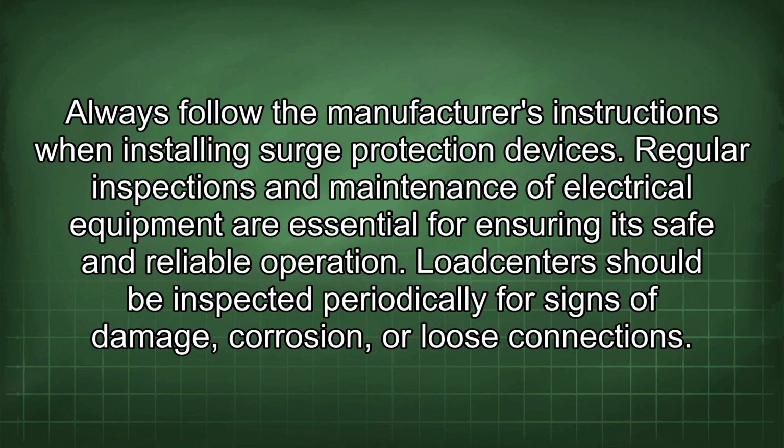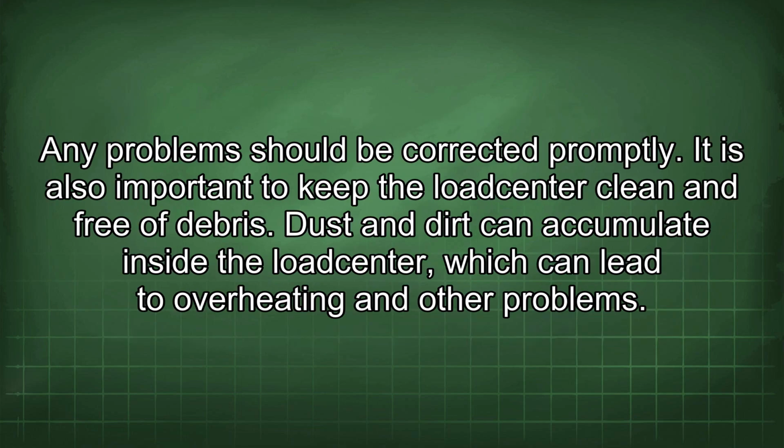Regular inspections and maintenance of electrical equipment are essential for ensuring its safe and reliable operation. Load centers should be inspected periodically for signs of damage, corrosion, or loose connections. Any problems should be corrected promptly. It is also important to keep the load center clean and free of debris. Dust and dirt can accumulate inside the load center, which can lead to overheating and other problems.